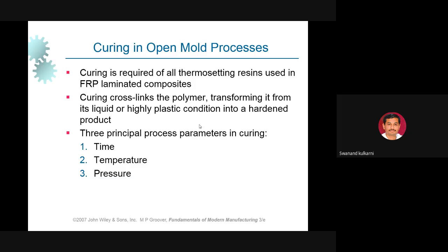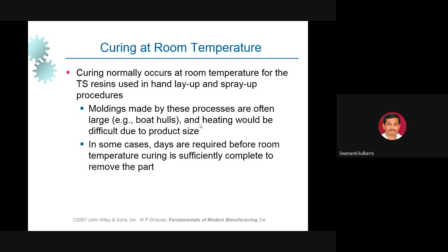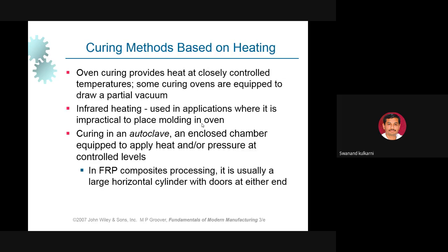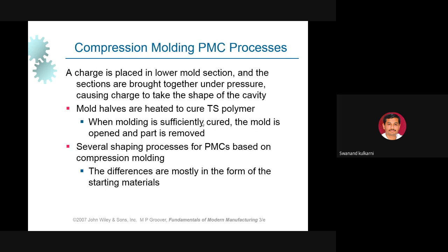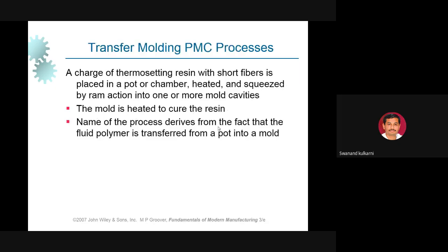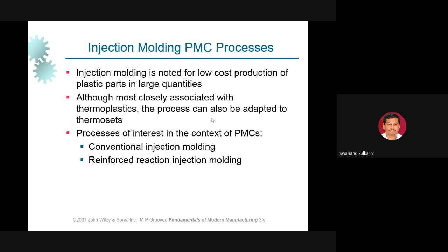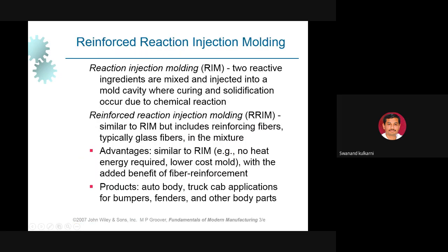in all cases, curing is one of the important parts. Curing is required, maybe curing at room temperature or curing at high temperature. This is because due to this curing, the particular strength or setting is going to happen, and due to this setting, the strength of the expected polymer matrix composite or pre-impregnated part is going to develop properly. Is it okay? Then